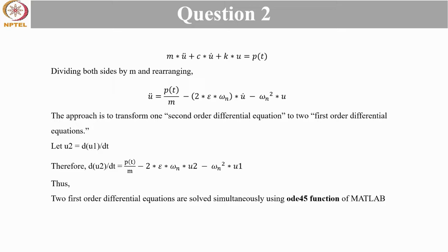And then we will use the ODE45 function of MATLAB, which helps us to solve two first order differential equations simultaneously. We saw this procedure in the last session, where we first convert the second order differential equation into two first order differential equations, and then solve them in MATLAB.